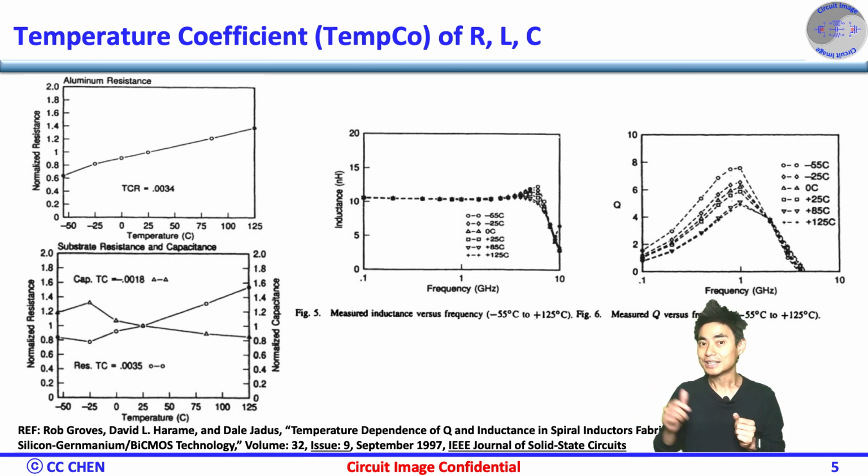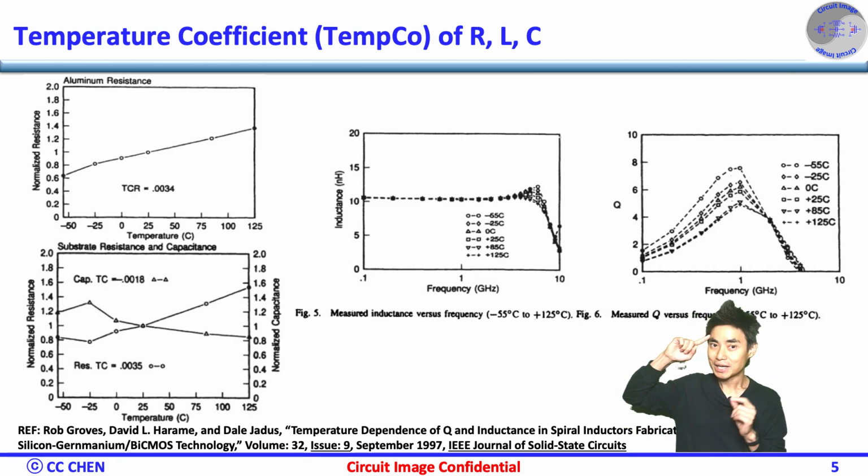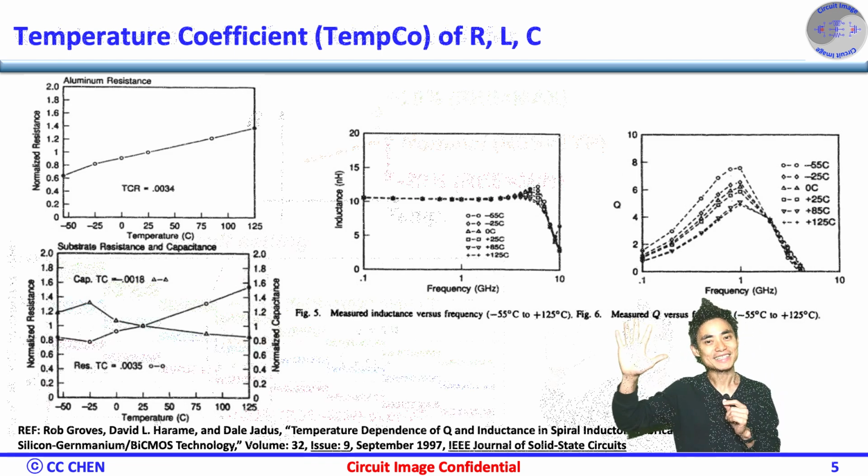Even for the inductance or capacitance, you should also watch out for the tempco if you are working on a precise oscillation frequency over PVT. What else should we look at carefully for the passive RLC? Think about the fabrication images for 5 seconds.